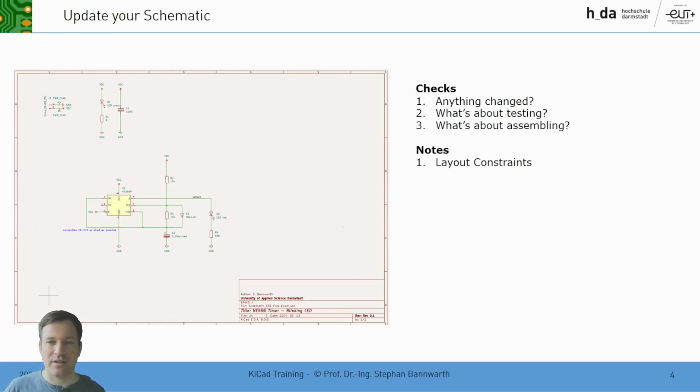This might be taking just a multimeter to check a voltage. This means also to take an oscilloscope to check a signal, or if you want to have digital data where you can put the logical analyzer to trace or to capture, for example, I2C bus or SPI or even the MIPI bus or USB bus. So this must be put into the account now, because otherwise you miss to enter the test points on your board. So that's the one thing.